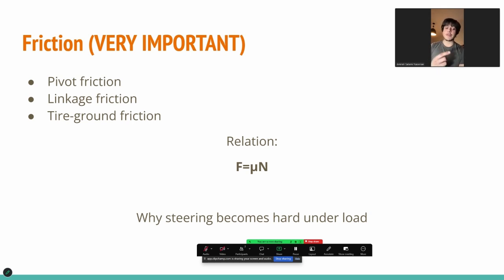This includes overcoming first the static friction, which is greater than the kinetic friction, and then also the kinetic friction. And because the vehicle is relatively heavy, the normal force is high, which also increases friction. This significantly reduces the effectiveness of the servo, making it harder to turn the wheels.